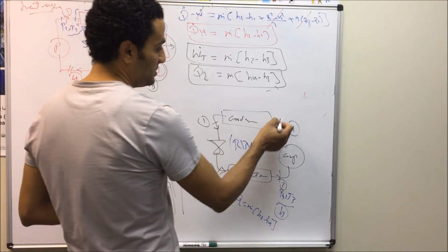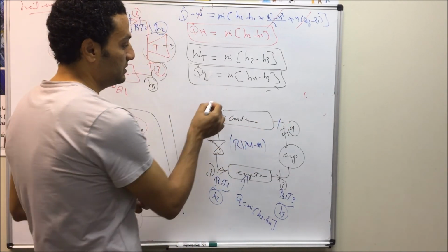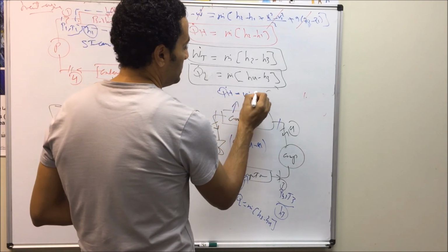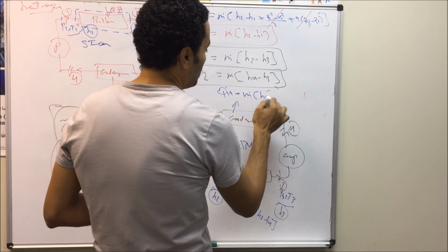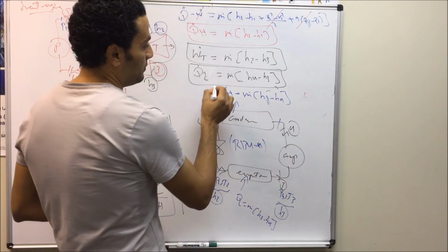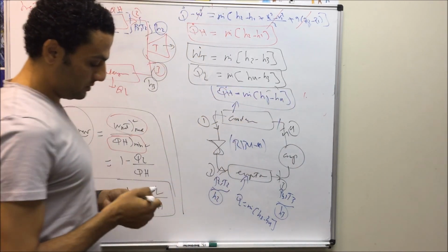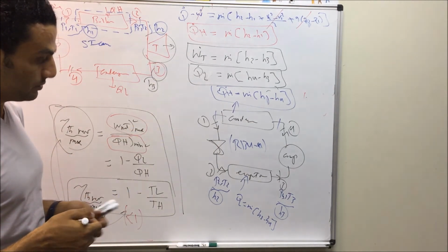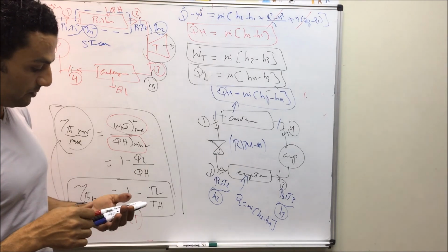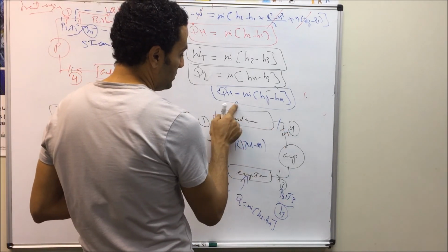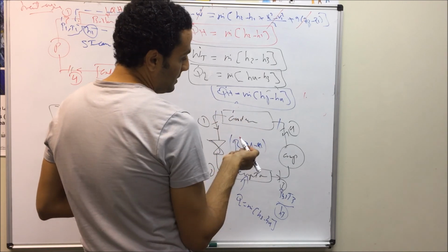So in case of the condenser, if the conditions 4 and 1 are given, in this case Q dot high will equal to the mass flow rate of the refrigerant multiplied by H1 minus H4. So if the conditions are given, then we can just calculate Q high and Q low, then we can substitute in the coefficient of performance. In some cases, he may not give you the conditions 1 and 2. He may say we do have a condenser.